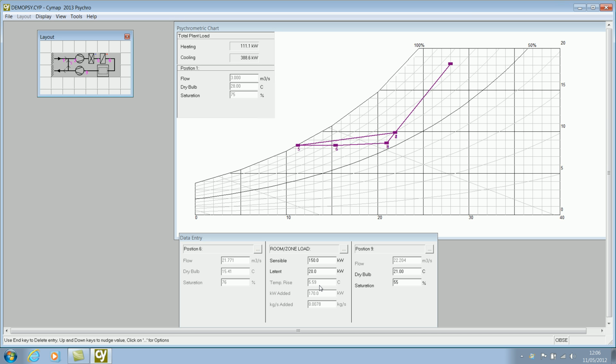A trap a lot of people fall into is trying to overspecify. Trying to specify a temperature rise and a supply condition and a room condition is based on an iterative cycle. He's trying to make 2 and 2 equal 5. You can't do it, so you have to relax some of the data entries, as I did earlier, by entering the 6 asterisks.